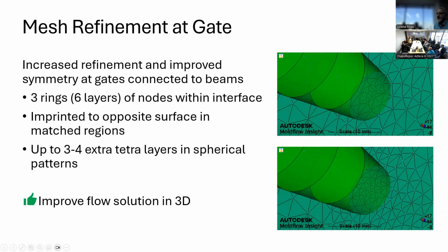The issue is that if the distribution of the nodes is not symmetrical, we can create a very asymmetrical situation, in the sense that if certain areas have nodes to map to and other parts of the runner system have nothing to map to, then we have locally a very asymmetrical situation.